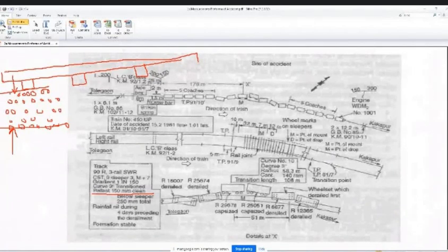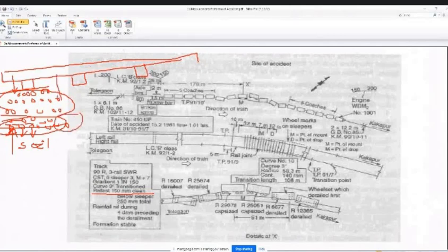So, this also the engineering department will confuse you. Normally the top ballast will be there, free stones will be there. The bottom is based on the soil. Say this is the soil. So, suppose the soil is black cotton soil or red soil or sand soil. Black cotton soil means this will stick to the soil, and some soil here also will be there. That type of soiled one should not be counted. That is why here it is written 150 mm clean ballast. So the top is called clean ballast, the bottom is called caked ballast.